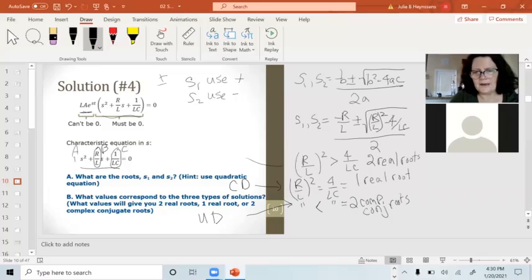And if I have 2 real roots, this is over damping. Yeah, there's a V in over damping. So you can look at that immediately, compare R over L and 4 over LC, and determine which type of damping you have. I could vary R by itself and change the type of damping.